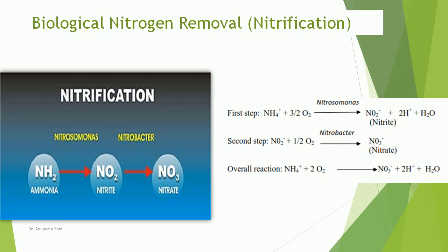Nitrification is a two-step process. In the first step, bacteria known as Nitrosomonas convert ammonia and ammonium to nitrite. These bacteria, known as nitrifiers, are strictly aerobes. This process is limited by the relatively slow growth rate of Nitrosomonas. Next, bacteria called Nitrobacter finish the conversion of nitrite to nitrate. Nitrosomonas and Nitrobacter use the energy derived from the reactions for cell growth and maintenance. The stepwise reactions of nitrogen oxidation that lead to the formation of nitrite are shown here.